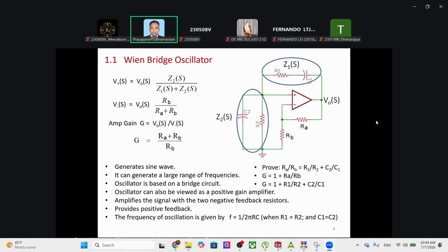So you keep R1 at some value, R2 at another. Again, you have maximum and minimum. So you have to calculate appropriately what is the fixed value of R2. Suppose you decided to change R2, what is the fixed value of that and what is the variable component of that, by considering the maximum and minimum of the oscillation in the lab. That maximum and minimum is different for different groups. Therefore, your calculation is going to be different. Okay.